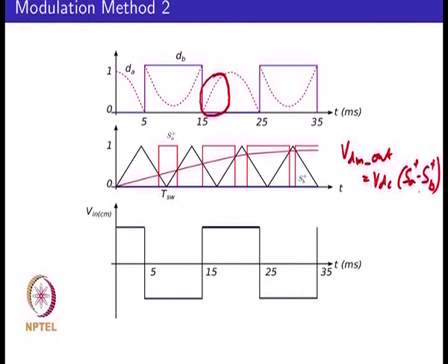So, you can see that despite the slightly more complex shape of SA plus and SB plus, your effective output voltage would be the desired sinusoid. If you look at your common mode signals that we had, we wrote an expression for V common mode of your input, which was VDC into half minus SB plus.